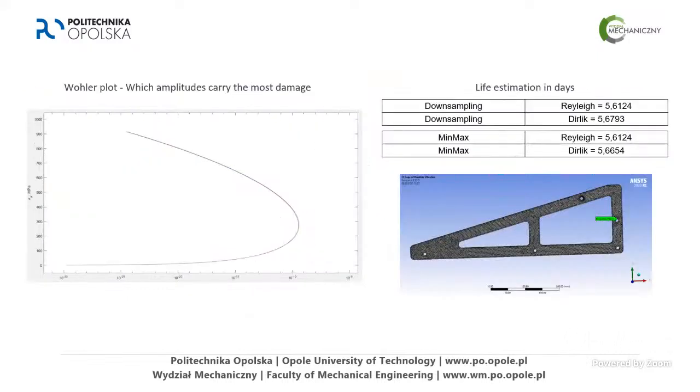And life estimation in days, in downsampling and min-max method. It's very similar. So the simplification we made has no large deflection, it's very similar. So we can make a simplification of the PSD in this case.